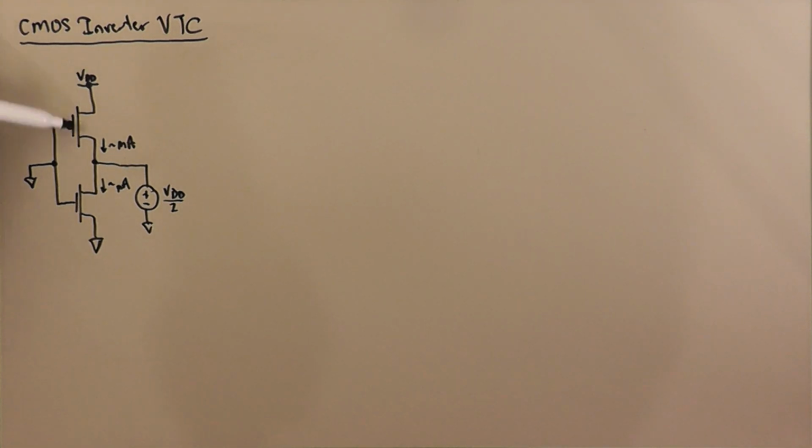But for the types of transistors we're measuring in the lab, the NMOS transistor with 5 volts on the gate and 5 volts on the drain would be passing about 4 or 5 milliamps. The PMOS maybe 2 milliamps or something like that. If we hold the output at half the power supply, assuming that's enough to saturate this PMOS transistor up in strong inversion, this thing is going to be blasting at saturation current, which is milliamps of current.